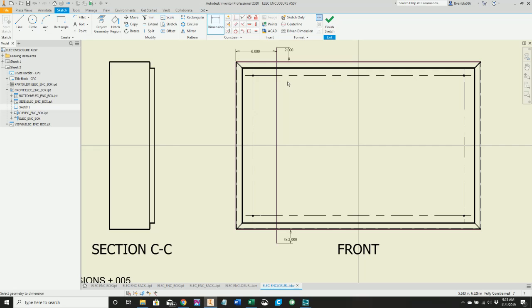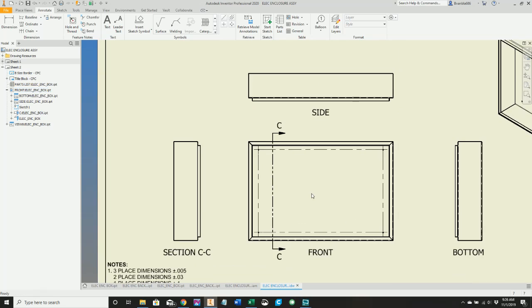So if the box changes and you don't have these dimensions in here, there's a very good chance that if it's a larger box, the cross section will actually break back wherever the offset is. So if your line endpoint is down here because the box increased in size, you're only going to see whatever that line is actually cutting through. So that's a super nice feature. Again, it's one of those things that SolidWorks doesn't have. It's sad that it doesn't have that, but especially if you're working with parametric models, super nice to have.